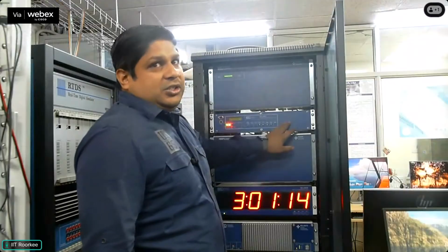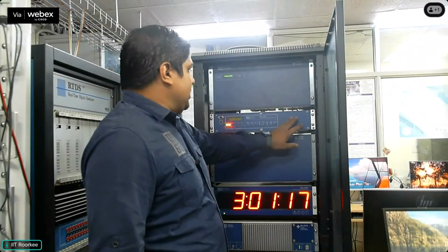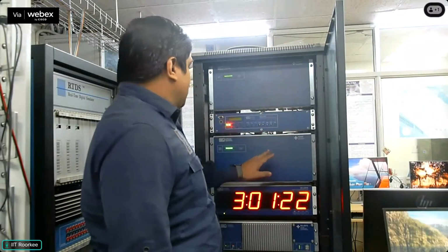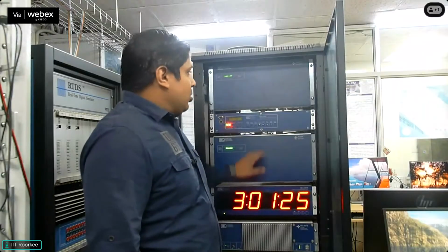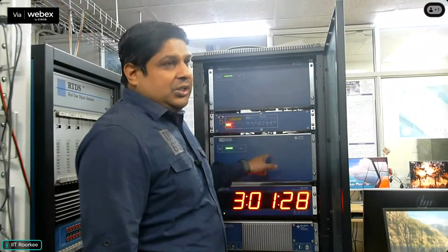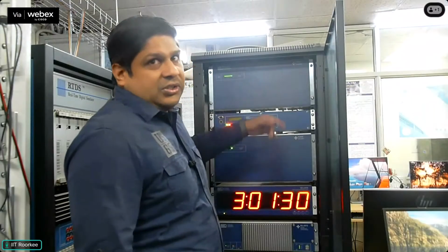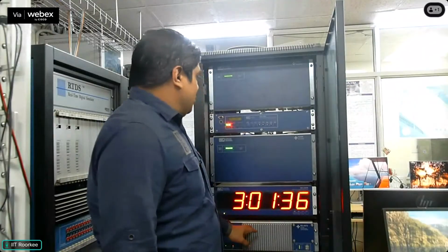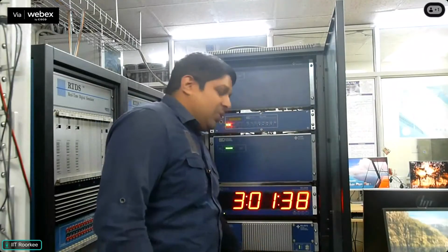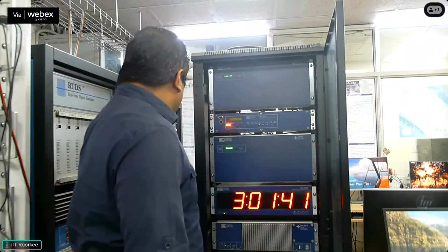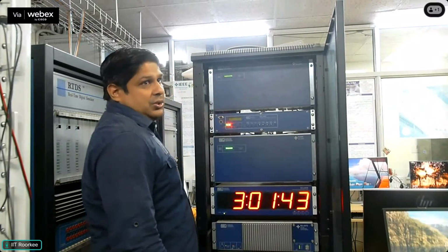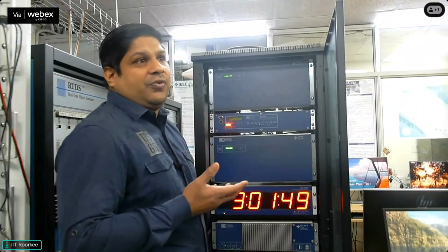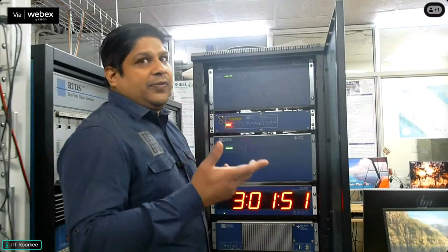And then this is a distance protection relay, a transmission protection relay, the SEL 311C. Most of the devices here are from SEL. And this is the GPS clock. All these devices are time synchronized using the GPS clock. I will show you the connections at the backside when we go there. And this is the PDC. All these PMU devices, 3 hardware PMUs here. And here we have a GTNet X2 card also. Using that card, we can have multiple software PMUs also, 8, 24, like that.